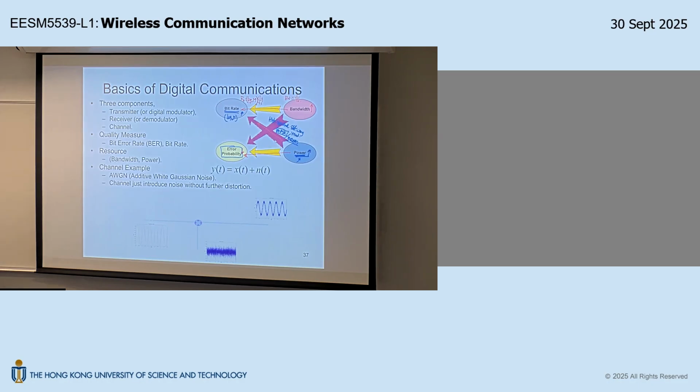The framework to consider is we have two resource metrics, right? One is bandwidth, one is power. These two will translate to money eventually, so it's the money cost that we want to minimize. But in this situation, if we pick this modulation family, what's the problem? You need extra power. Where does the power come from on the satellite? It's a solar panel. So if you need extra power, that means you need a bigger solar panel. So what's wrong with a bigger solar panel?